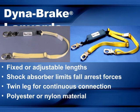Now, let's talk about some key features of these lanyards. First, they come in fixed or adjustable lengths, giving you flexibility depending on your working height or preferences. Next, the shock absorber limits fall arrest forces, which is crucial for reducing impact forces during a fall and protecting the worker. We also have the twin leg design, which allows for continuous connection, meaning if one leg is temporarily disconnected, the other remains secured, enhancing safety during movement.